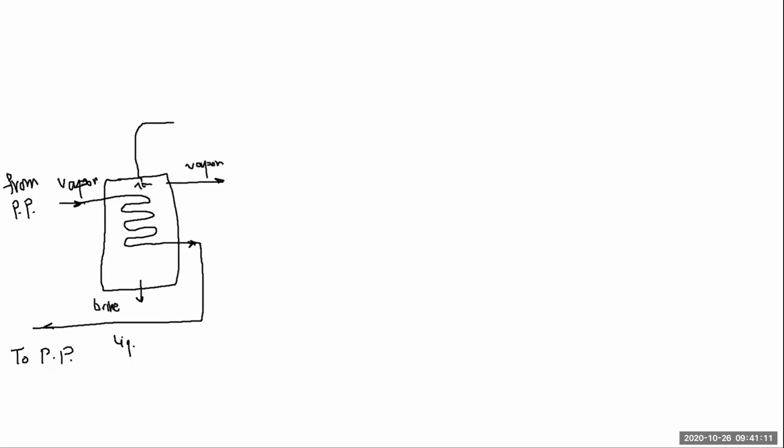The point here is, we said that one of the drawbacks of this system is that we are losing the energy because this vapor is going to be condensed into liquid. So the latent heat of condensation goes by preheating the seawater. This is somehow useful, but this one is thrown away to the environment, and this is a loss. So instead of doing that, we add another unit,